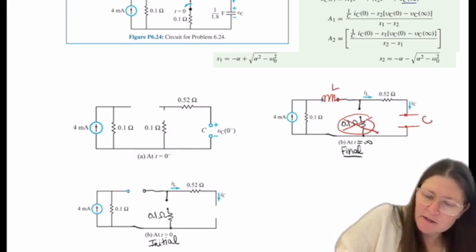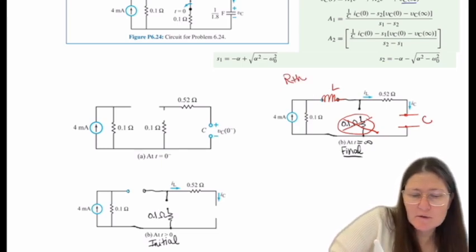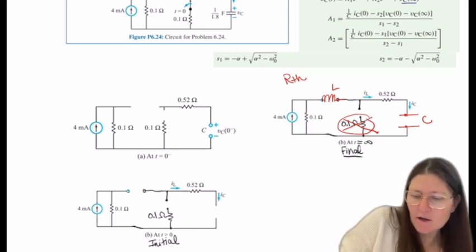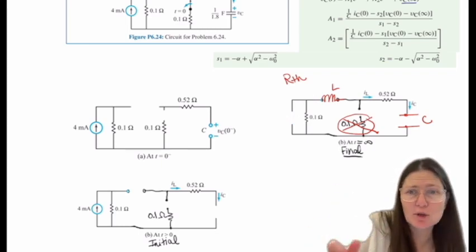So to get RTH, what happens with the current source? Okay, it will go to an open. Remember, I equals 0 looks like a floating wire. So that's how you can remember that it's open, right? Floating wire means no current flowing in it.